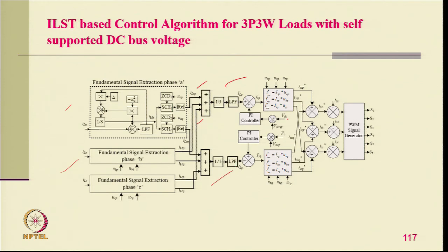Then we have the DC link voltage control and the terminal voltage control, which give the reactive power, and minus the load power goes to the reactive component on the generator side. Using a template we get the reference reactive current, we calculate it from the amplitude, and with the phase template we get the active component, and we add them together to get the total generator current. Taking the feedback current, we go to the current controller.